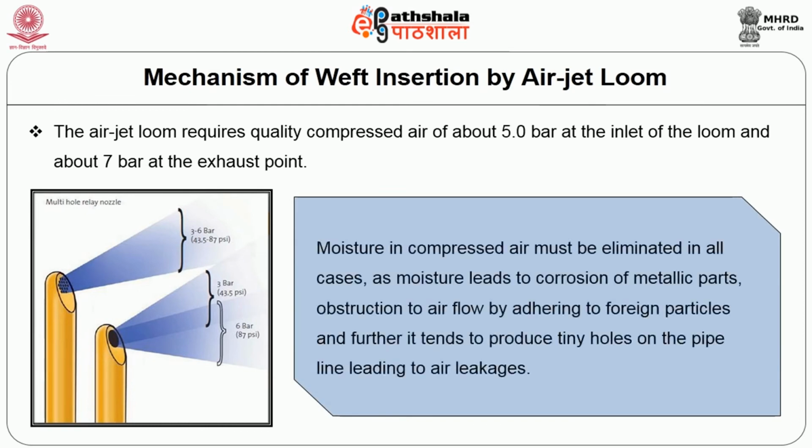Moisture in compressed air must be eliminated in all cases, as moisture leads to corrosion of metallic parts, obstructs the flow of air by adhering to foreign particles, and further it tends to produce tiny holes on the pipeline leading to air leakages.